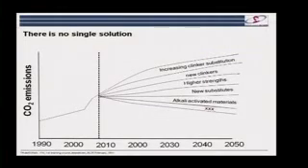We can look at increasing substitutions of clinker. We can think about new clinkers. We can think about higher strength concretes. We can have new substitutes. We can have alkali activated materials, etc. And if we use a combination of these solutions, I think this is the only way we can see to keep the CO2 emissions associated with building under control. And this approach is what I call an open concrete approach. We have to be able to use a wide variety of different solutions.